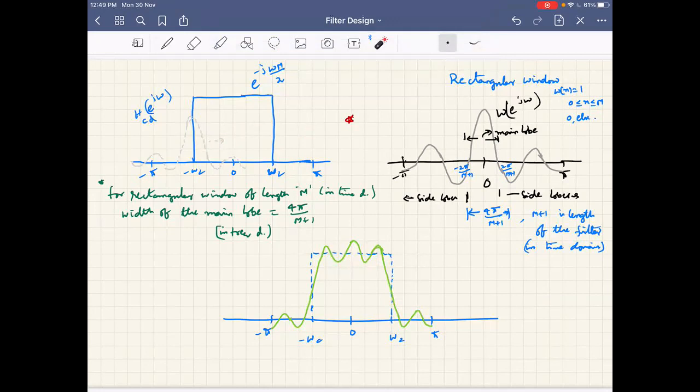And these oscillations are because of the side lobes. So for the practical filter, you can see that though we wish to attain complete zero attenuation here in this range, that means we don't want to pass any of the frequencies, however we may pass some small frequencies in the stop band as well, in the practical design of the filter.